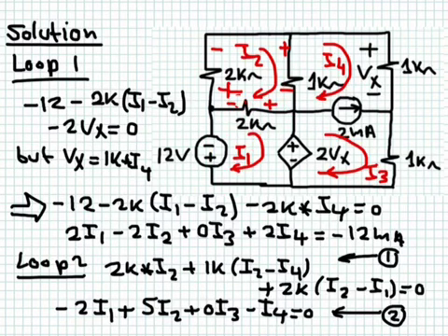Or I can take it the other polarity, this way, and because I'm going in the clockwise direction, I will count it as negative, and it's going to be 2K (I1 minus I2) as I write it here. Both of them are the same. So you say it is plus 2K (I2 minus I1), or it is minus 2K (I1 minus I2), exactly the same quantity. You continue to go around the loop, and you get this here positive, negative.